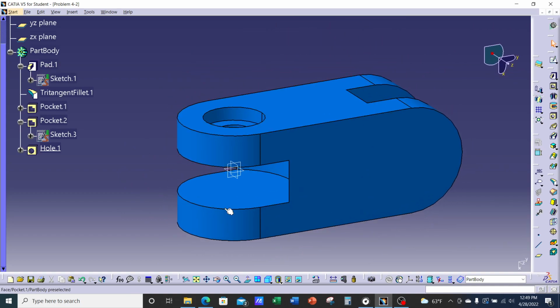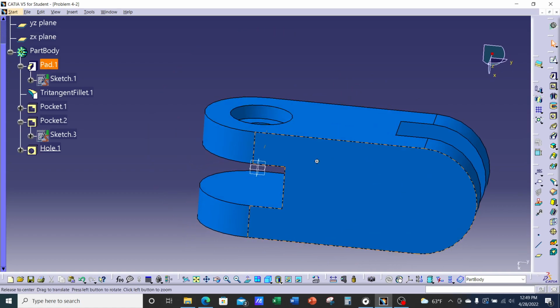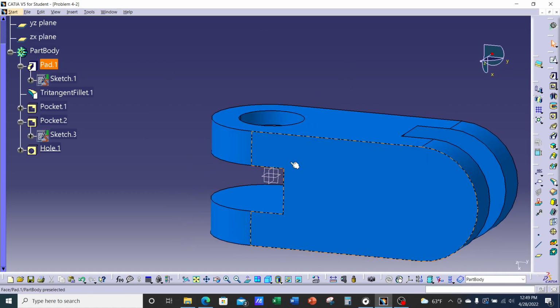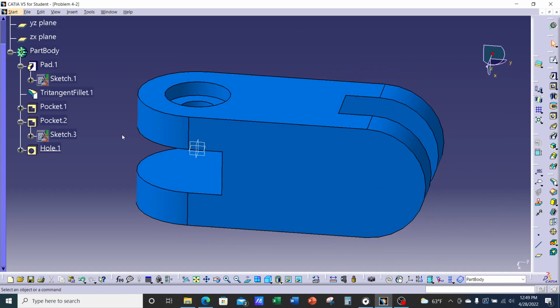Okay, so instead of repeating it over here on the bottom, I can do a symmetry if I want to. Or I can just do it 3 more times so we can have a total of 4 counterbore holes. One option you can do is mirror it. So I'm going to pre-select the hole and say, hey, I want to mirror. So here's the mirror command.